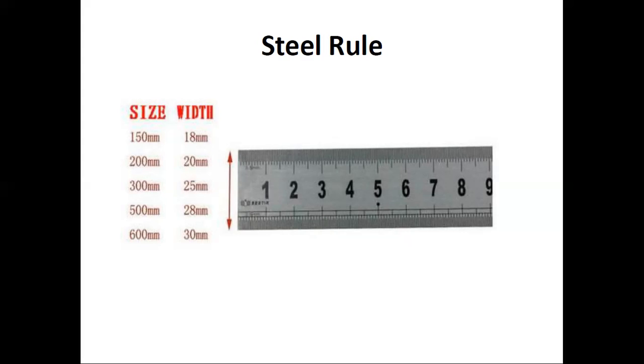For a finished product, a precision measuring instrument like a vernier caliper is used. Okay, and if you have the length of raw material, then you can use the steel rule. Simply mark it and cut it from your whole section for the further operations.